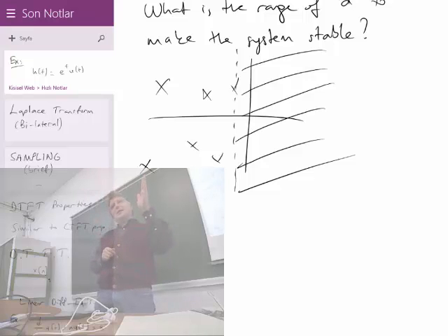Some of the poles may be at the left, some of them may be at the right, and if their region of convergence intersection is in the center, including the j omega axis, for us it is fine. It is still a stable system. But control system people don't like it because in physics you do not have a non-causal system. The physical systems are already causal. They are always right-hand sided. So they just assume that it's causal, so the poles must be at the left-hand side. That's it. But for our exams, that's not true. You must draw the region of convergence and make sure that the j omega axis is included inside the shaded area of the region of convergence.